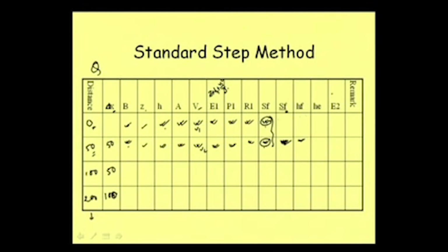So taking that V1 and V2 we can calculate the energy loss, HE, and then if we sum up these values, SF, HE, and then Z, H and V square by twice g, all these things will give us the calculated value of E2.